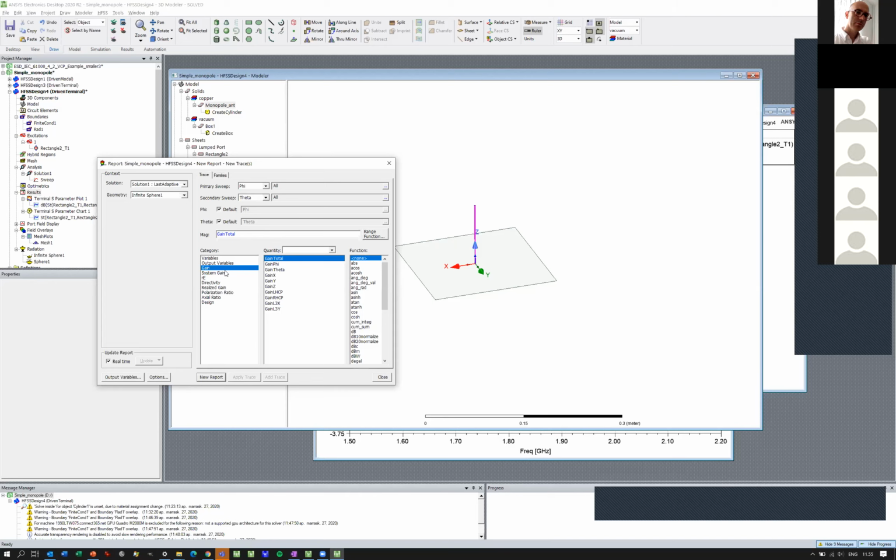The difference is whether you are willing to include, for example, if you are using an excitation circuit to drive the system, you can add matching components in SPICE and excite the system by using them. You can also see whether it is accepted power or received power of the antenna element. But let's use the simple gain and total gain.